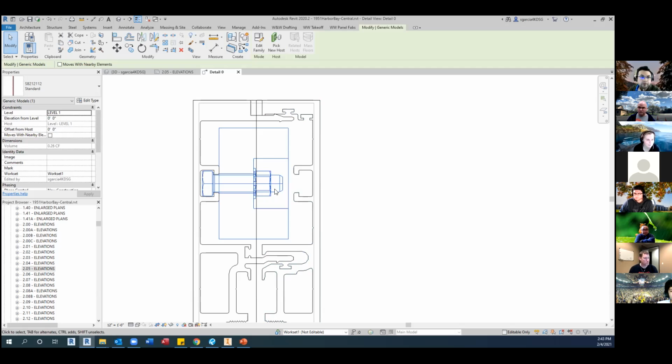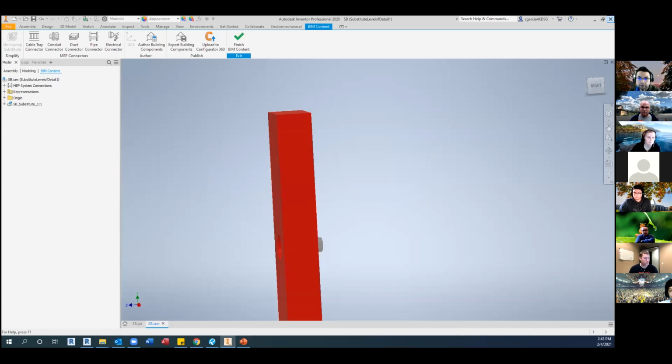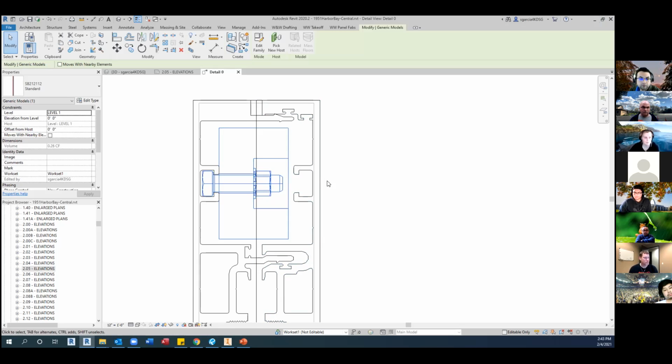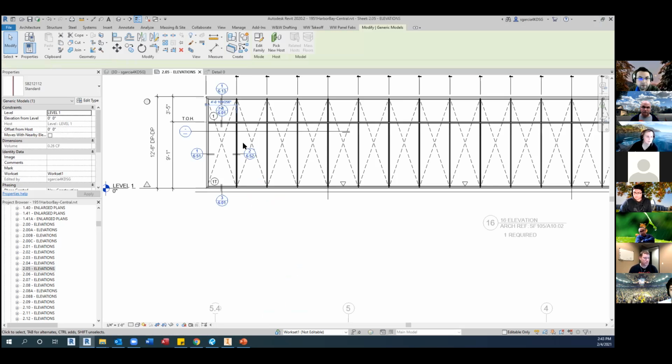But at this point, I mean, you guys, for example, are thinking to use parameters, but to me, I don't need those parameters on Inventor because at the same time as you are placing this steel bar, I can continue my path for creating fabs, and I can model it directly from my parameters that I already have on Inventor, right? Yeah, that is so right. But it's placing it on 0, 0 elevation? Yes. I see. Yes. So you can adjust it from there.